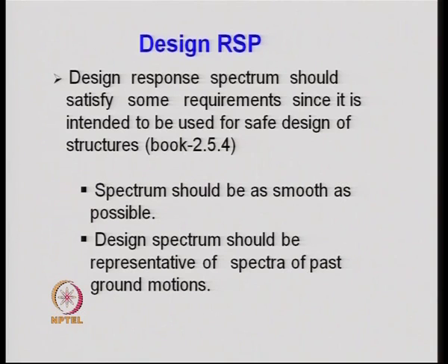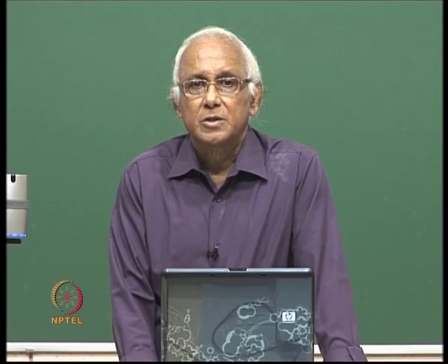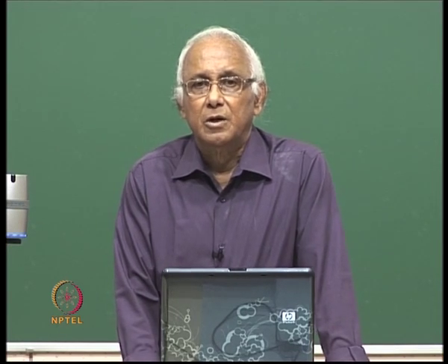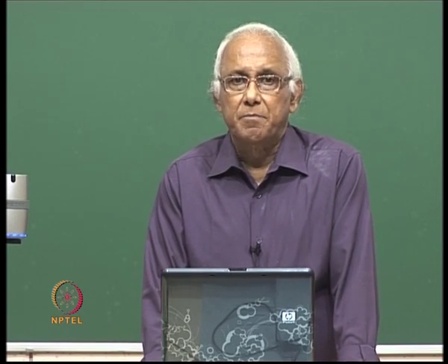If the design response spectrum is not smooth enough and it changes rapidly with time period, then there could be a sudden change in the value of spectral acceleration for a small difference of time period.